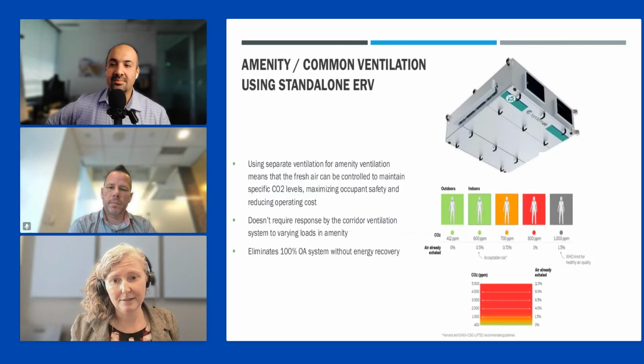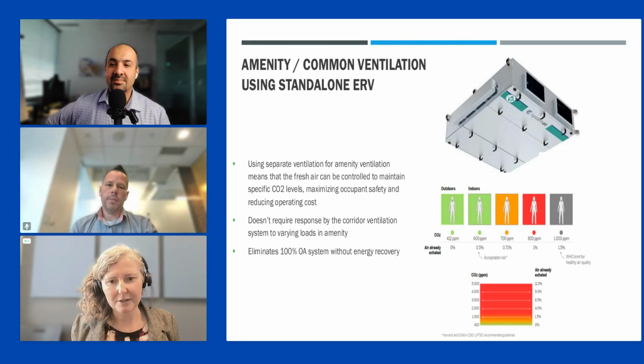I like to put an ERV in my amenity spaces because it means I can turn it off overnight or when the building isn't occupied. So again, this is savings for you as a long-term building operator and savings in the energy model.